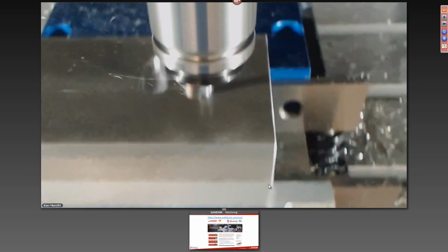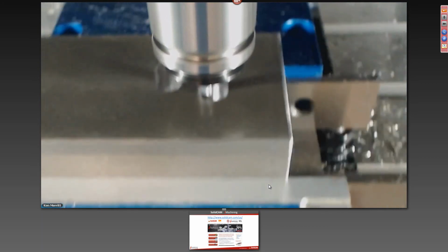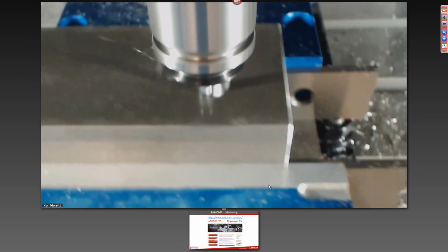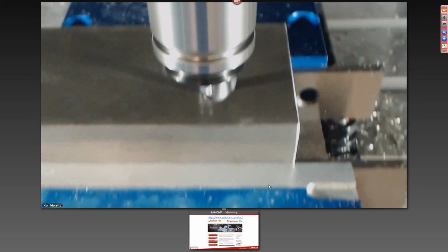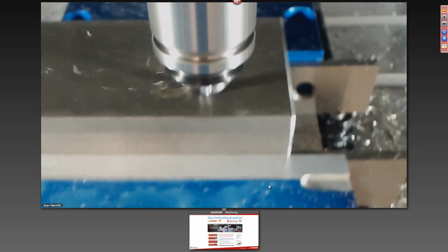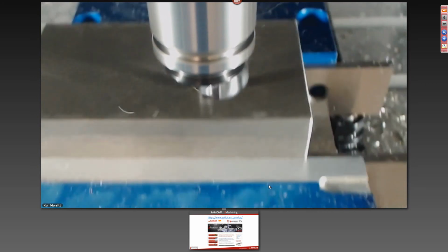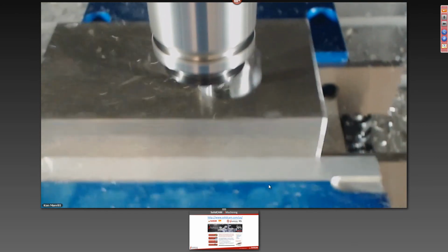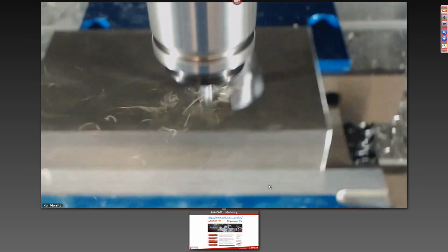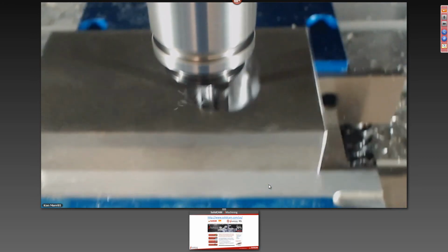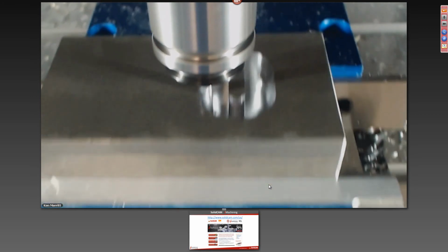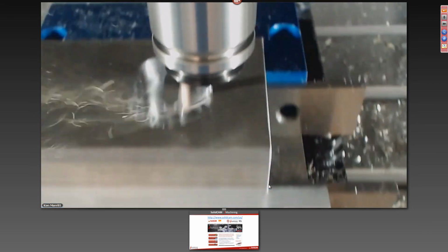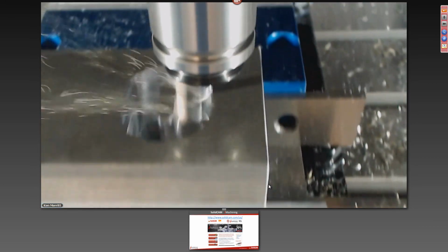Yeah, Ken, that's another really great point too. I'm glad you mentioned the spindle load, because just because of the algorithm and the way iMachining works, it flies in the face of what you would think of traditionally. A lot of people say, well, you can't bury a tool that deep without causing extra wear and tear on the spindle bearings and things like that. And it really is the opposite. It almost seems counterintuitive. But you can see here the amount of material that we're removing so quickly is just amazing.